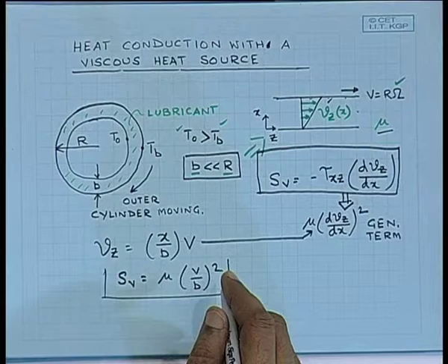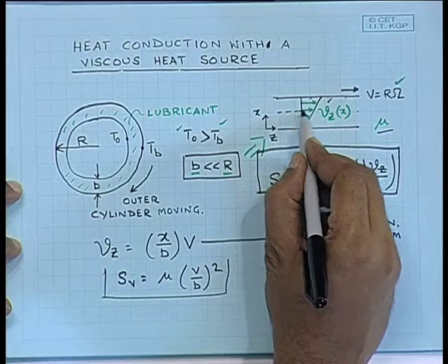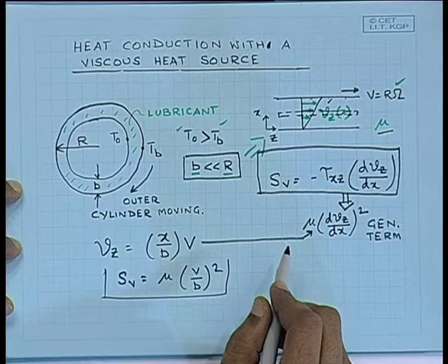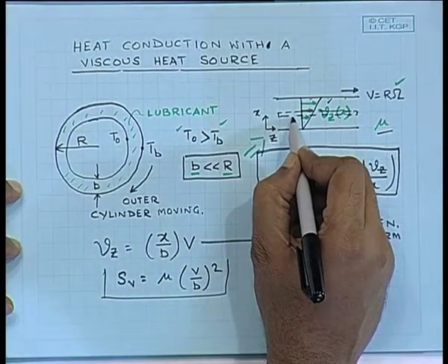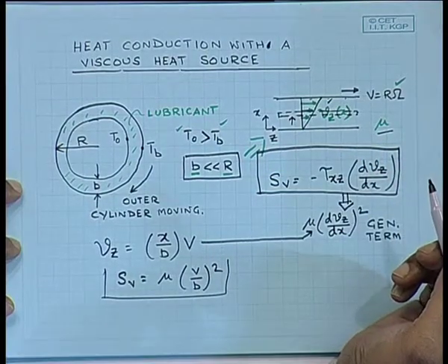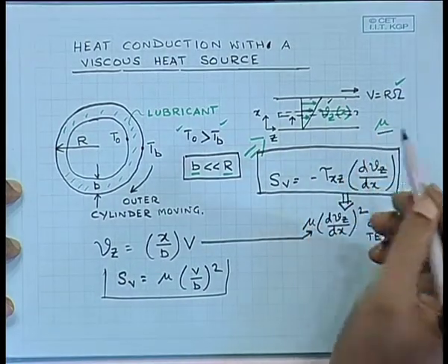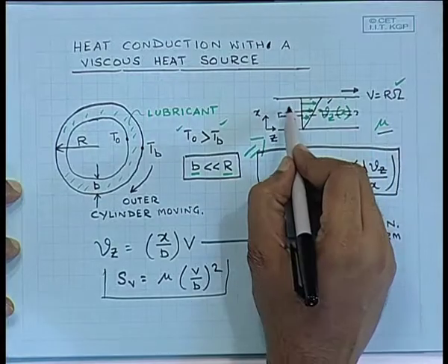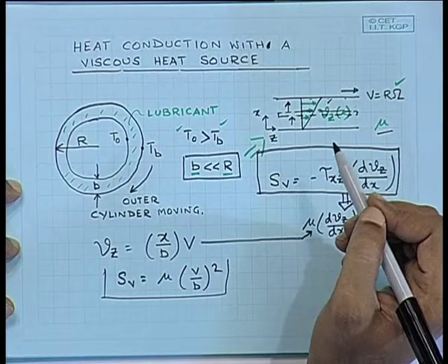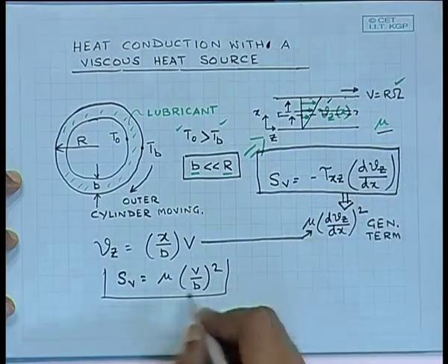Now, how do we analyze the thermal part of the problem? We can assume a thin strip of thickness dx, some amount of conductive heat is moving into this. The amount of conductive heat would simply be equal to the area of that thin strip multiplied by Qx, if Qx is the flux. The amount that goes out would be the same, whatever be the area, only Qx evaluated at x plus delta x, and you have the source term.